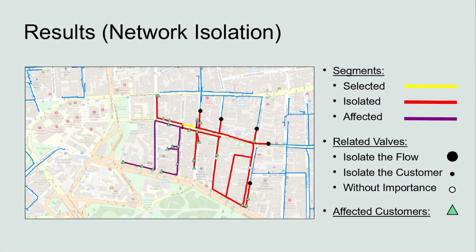All these kinds of problems must be corrected so we have the correct manipulation of our network. This is network analysis. After this, we have network status. Based on reservoirs and open and closed valves, I have code that defines if the network is supplied or unsupplied. I use blue for supplied and black for unsupplied. Green for open valves and red for closed valves.